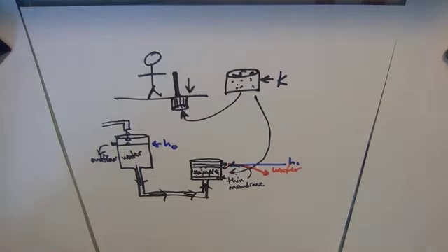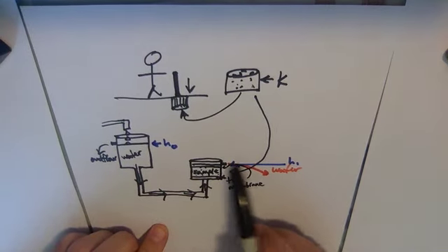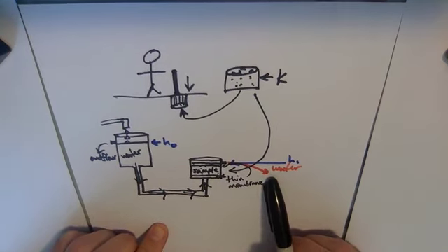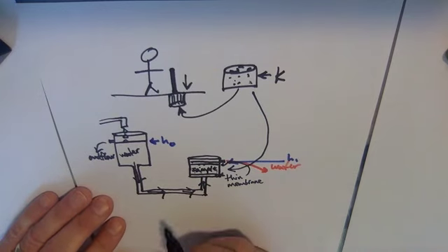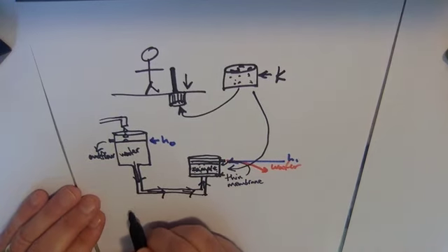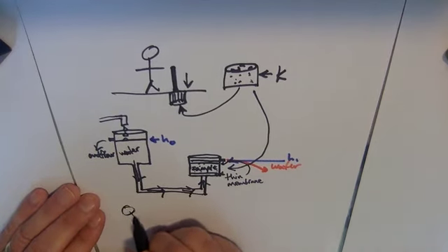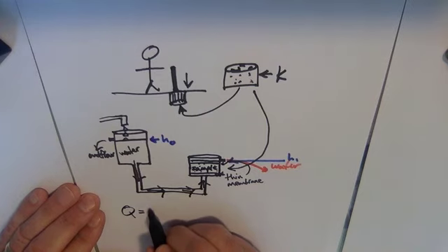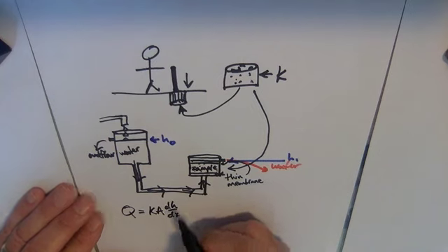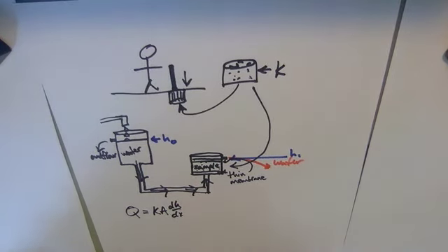And so by measuring the rate at which water comes out on this side over here, we're able to actually calculate the hydraulic conductivity. So if we think about Darcy's law with capital Q, it's Q equals K A dH/dx. Again, I'm not going to worry about the negatives because that gets taken care of when you do the subtraction. So I'm just going to drop it for ease of saying.